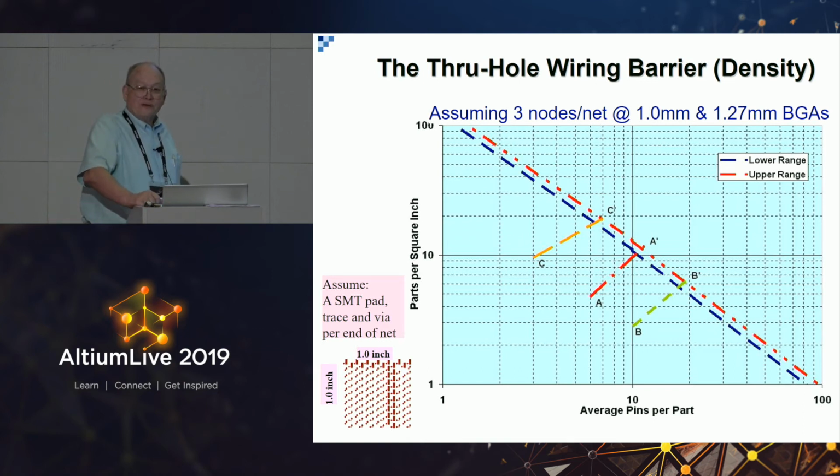If any of you ever run into your placement and now you're trying to connect, and all of a sudden you've run out of places to put vias, you've hit this wall. Because unfortunately, bosses tell you, do it this way without looking at the numbers. And you're up here, and they tell you you've got to do it as a 12-layer multilayer.